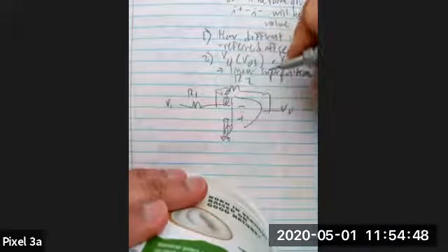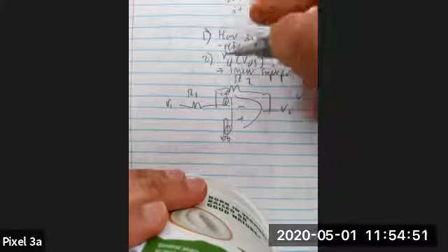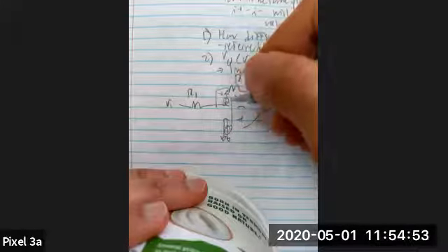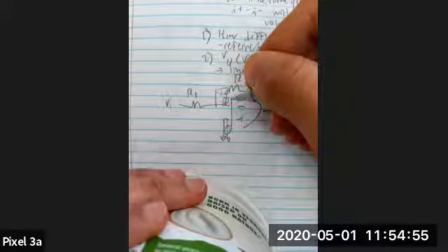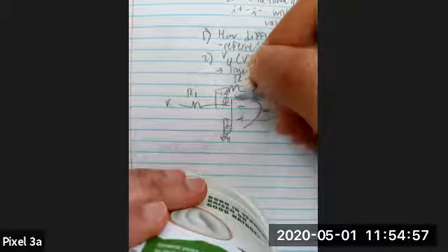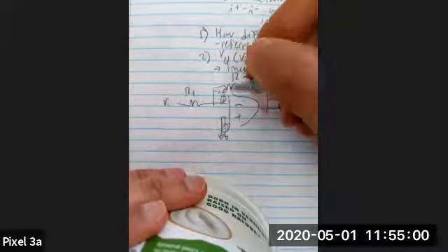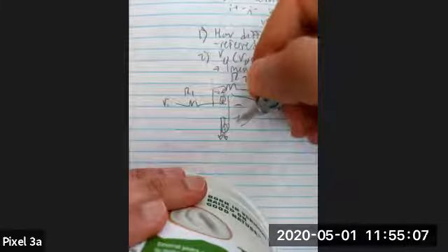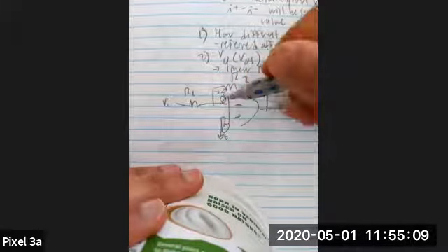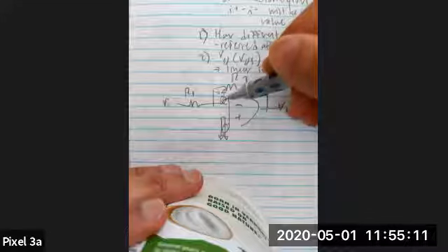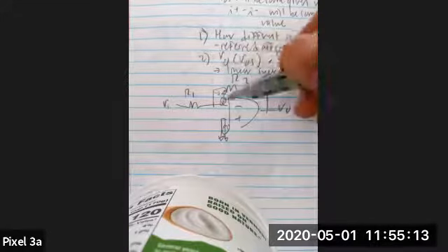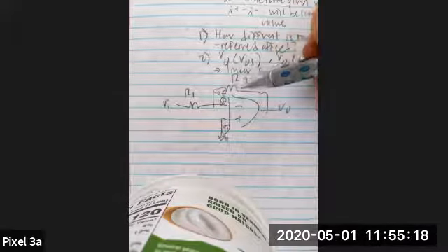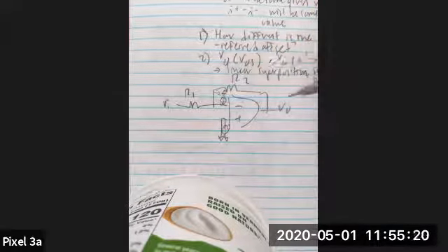It is actually easier to say that all of the current goes through this source, because that will give you your worst case output offset, as opposed to current going through this source and going to ground in the case of infinite input impedance. So our worst case offset comes when the current goes through this source, and then you can find the effective output voltage as a function of this current just by virtue of the current going over a resistor or something like that.